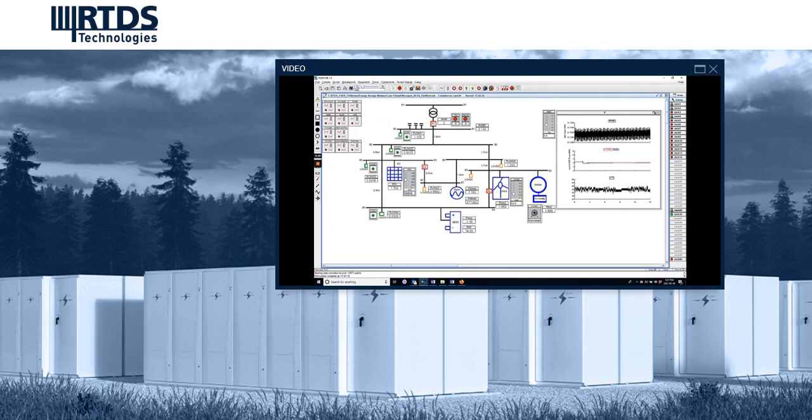If there is a reduction in the PV power output, it will be picked up by the droop-based response of the battery and the diesel generator. With the flywheel now in discharge mode, with a reduced PV output, the power balance is still maintained in the microgrid to supply the loads.